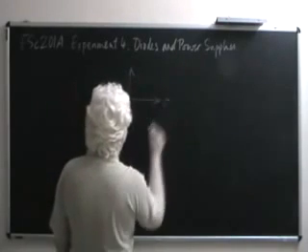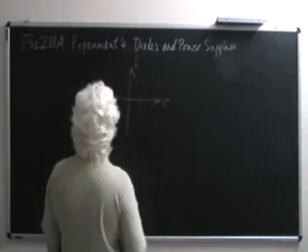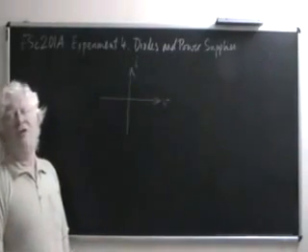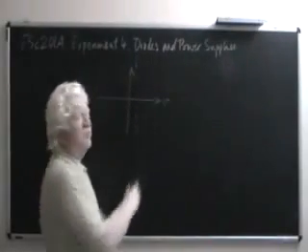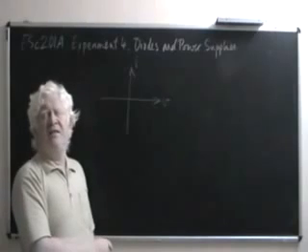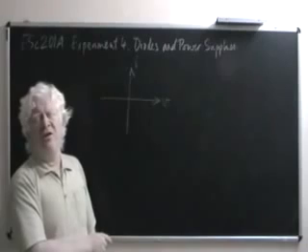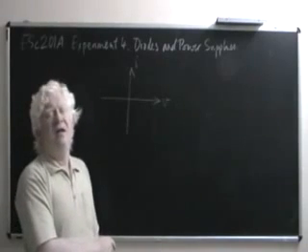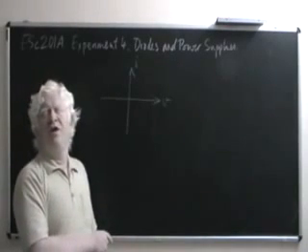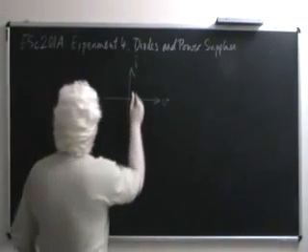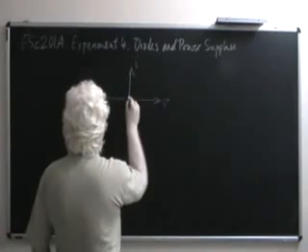This is the voltage axis, this is the current axis, and as I said, when you apply a forward voltage, that is to say when the applied voltage is positive, then it acts as a short circuit, so any amount of current can flow through the diode without giving rise to a voltage drop across it. So you would have a characteristic like this.